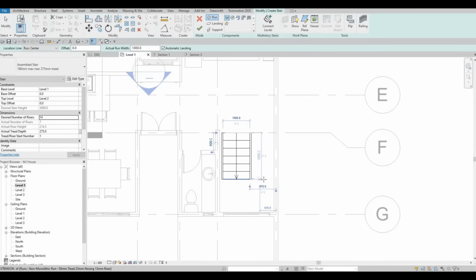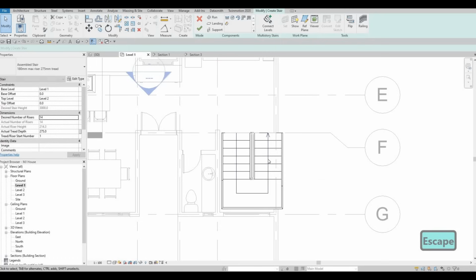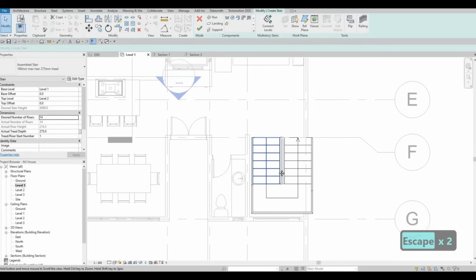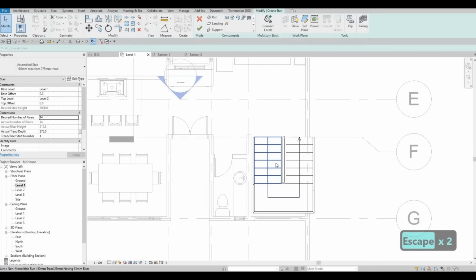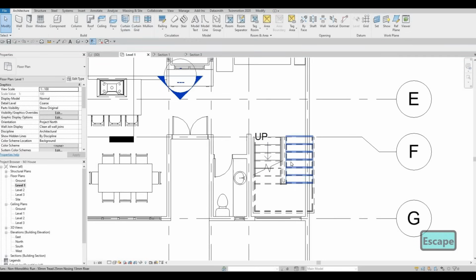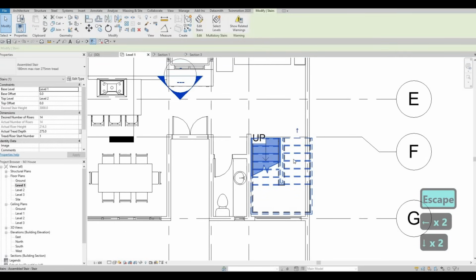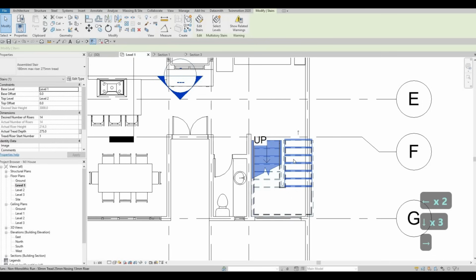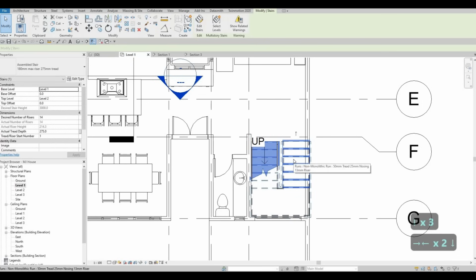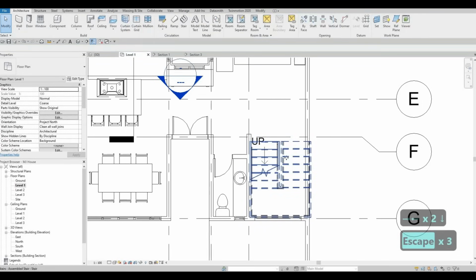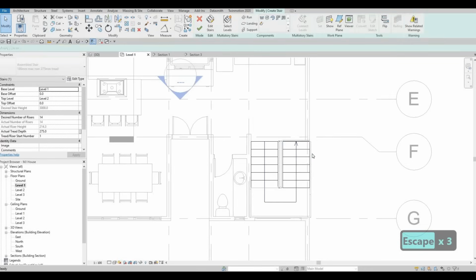So click that, and then let's go back here and then click it again. Don't worry about the spacing. We're going to figure it out later on. So once you do, click on finish, and then select that again. We could just move it in place right now. Don't worry about that. And then edit the stairs again.